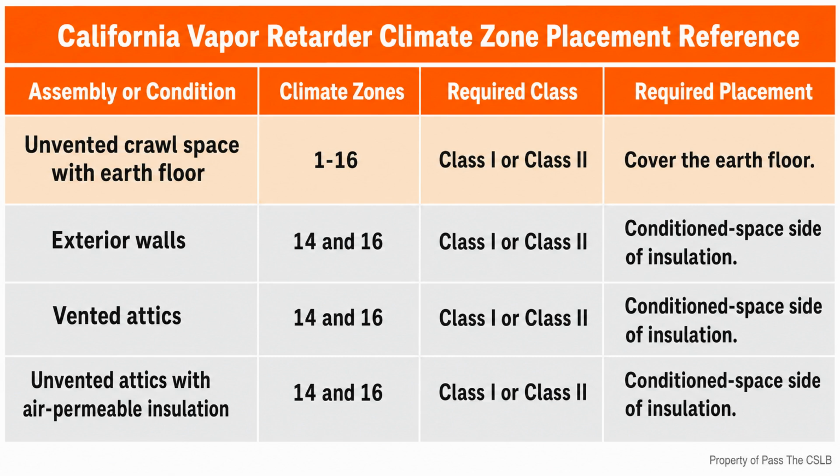The order matters. Soil is below, clean aggregate creates the break. The vapor retarder is next, and the concrete is directly above it. Suppose a crew places the vapor retarder under the aggregate, because that position seems protected from foot traffic. That changes the required relationship.